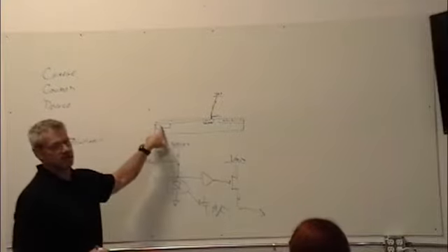And the diode was actually less than that, because if you look at it from the top, what we would do is put in a deposition, and the diode actually ran like this underneath, and then there was a tie here that brought it off to all that other circuitry. So the diffusion region was actually only this area around here.